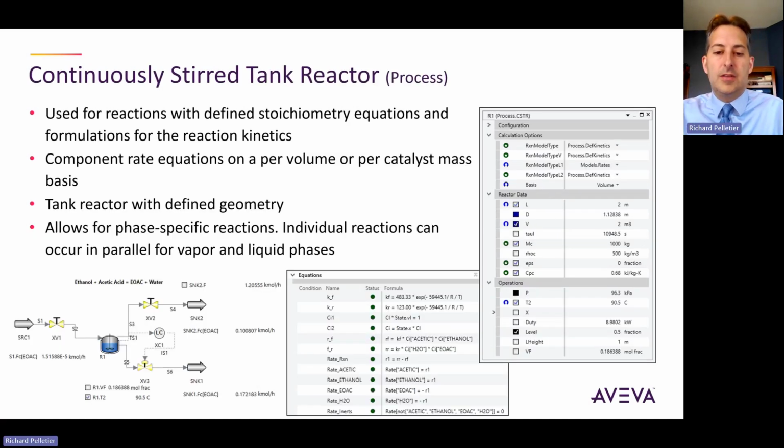Here's the example of the kinetic data. You can see kinetic equations up here, and down here we can see our rate equations. Ironically, with this specific example on the slide, we do see the relationship here, R1 being used in the rate equations, and then R1 relating to RR and RF, which are part of the kinetic data. But this is an older screenshot of the way that we used to write these reaction submodels. You might not always see it so cut and dry in the way that the reaction tool generates the reaction submodels.